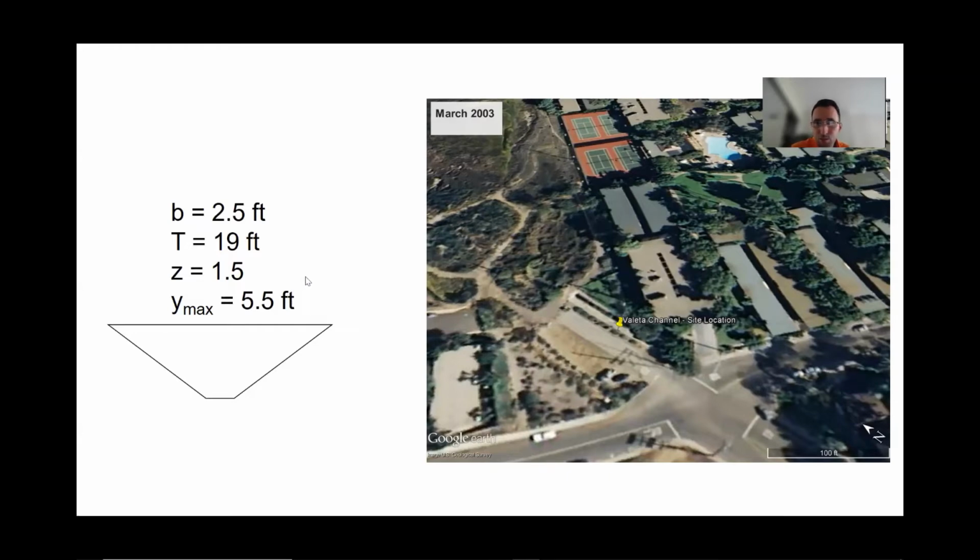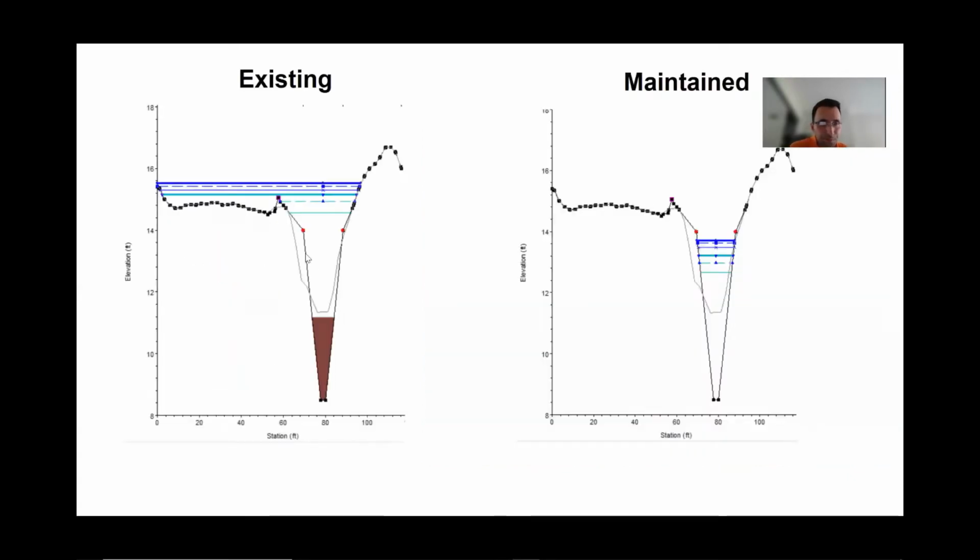And as we do that, we can also make our existing model able to have features like culverts. Right now, because it all shows as surface of the earth, we can't really put a culvert in that. The way we do it is basically we model it. Right now, this light gray line is showing the situation in the model.